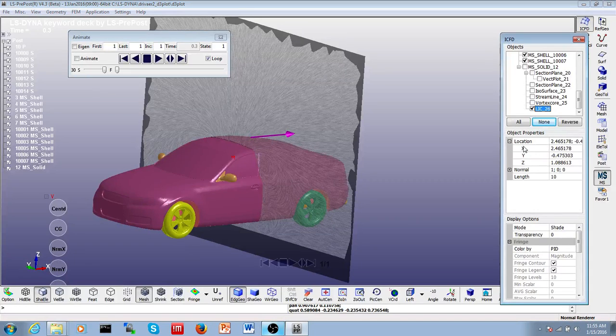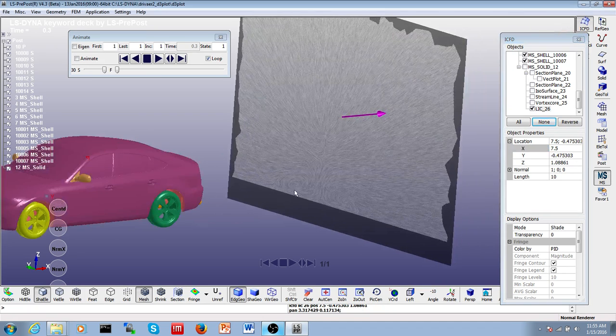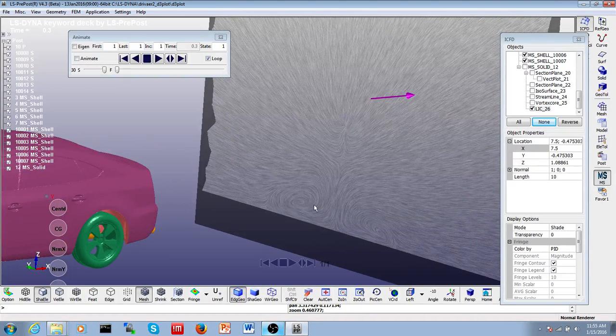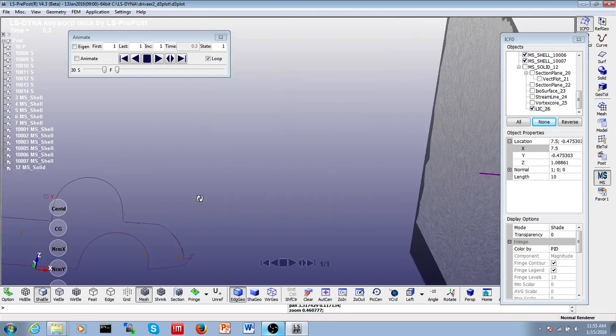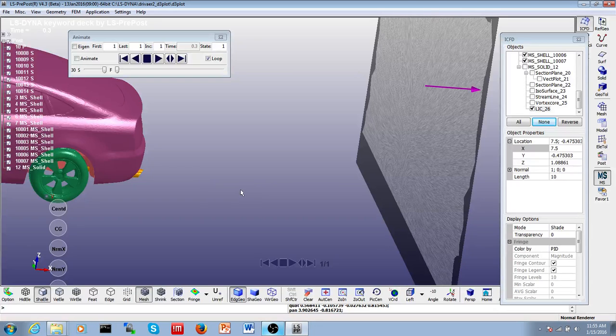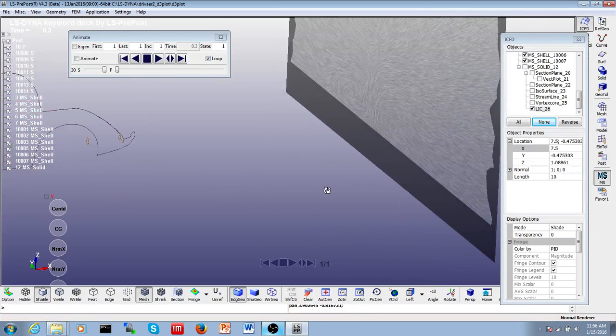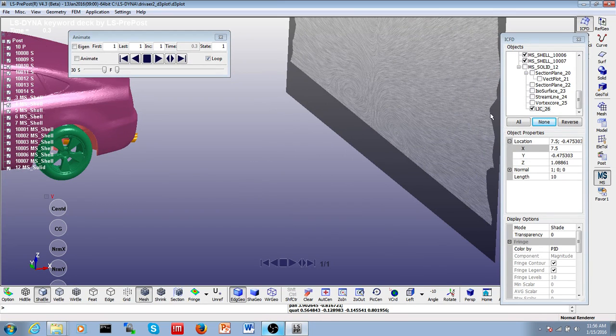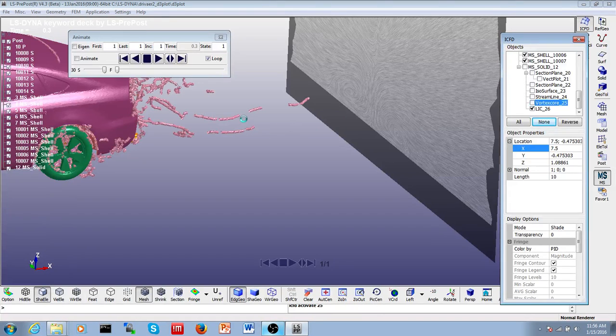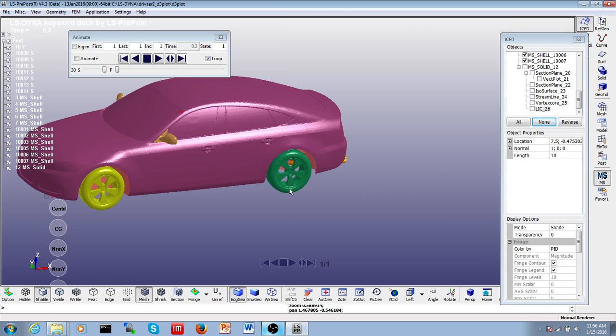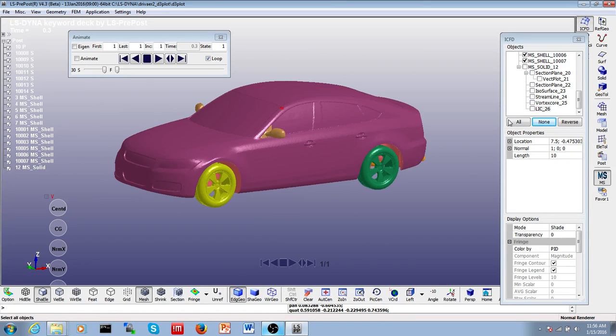If I move it a little bit, let me go around the car, or at the back of the car, rather. Now I'm at the back of the car. I see that the flow is almost smooth, save for those two little eddies at the back. Here we are now maybe 3 or 4 meters, 12 feet, at the back of the car, and we see that the flow is still not completely smooth. We see those two, probably the consequence of the trailing vortex cores that we have seen here previously. So all in all, this is what I wanted to show you regarding those post-treatment tools